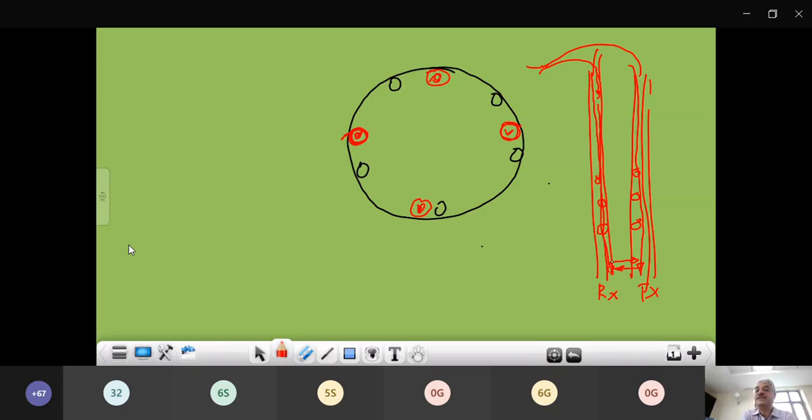So these signals, see, if there is no discontinuity, then the time this takes to go there, this receives, that is constant. Then from this it comes back and again goes there, then second receive, that is constant, that is recorded, and based on that some charts are plotted like this. So if your chart is coming like this, it means uniform. Suddenly if there is something wrong, if this time is increasing somewhere, it means there is some discontinuity here. Then you put it in another 2 holes and pull it out.